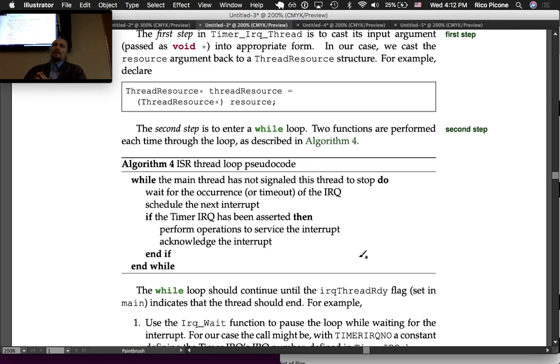Because the IRQ, would it be pretty obvious that you're missing them? It would be, because if you're looking at, say you're just passing the value through, you read it and then you write it, and you're missing them. And you could even do this. You could put your wait function in there and intentionally miss it, or do a little for loop in there that just takes a while. Have it add 2 numbers together like 1,000 times or something, and then make it miss.